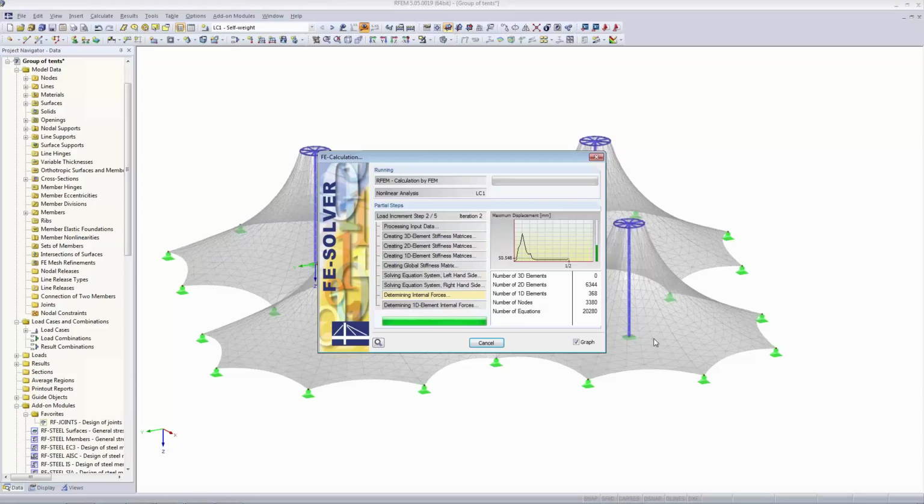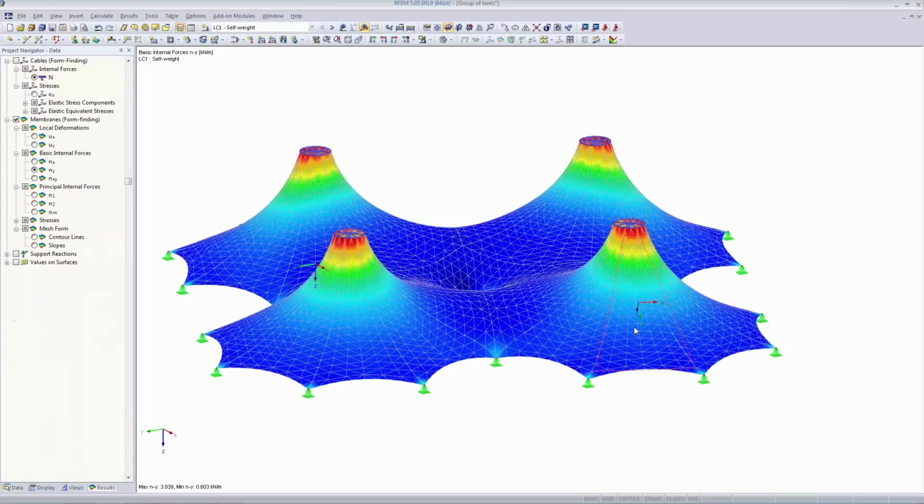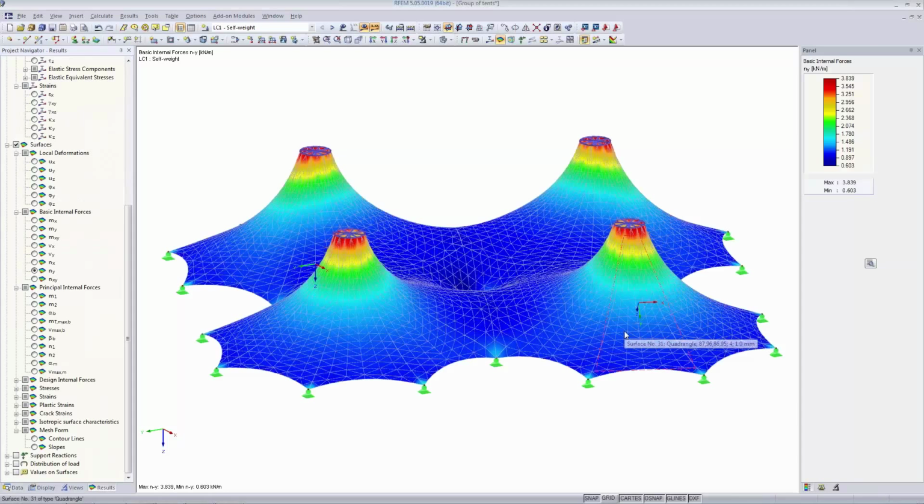What I think is that you need the fixed supports for the form finding process itself, but you don't need these fixed supports as soon as you have found the form and everything is stable. You could cope with just a hinged support down there. This would mean in practice you don't actually need to build up a fixed support. You can just make it an intermediate fixed support. So let's have a look at the results of self-weight now.